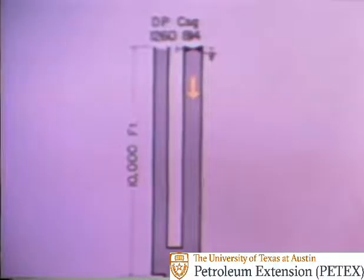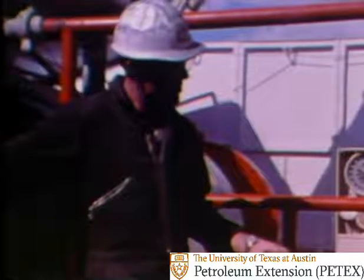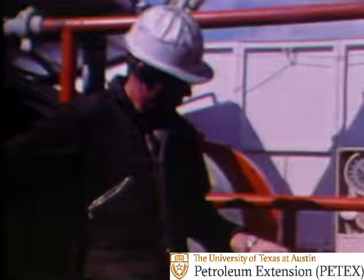When the choke is being adjusted, the driller must remember that there will be a time delay of approximately 1 second per 1,000 feet, measured down the annulus and back up the drill pipe, before the pressure increase or decrease appears on the drill pipe gauge. The time delay means that in our 10,000-foot well example, there would be at least 20 seconds after making a choke adjustment before a pressure change will show on the drill pipe gauge.